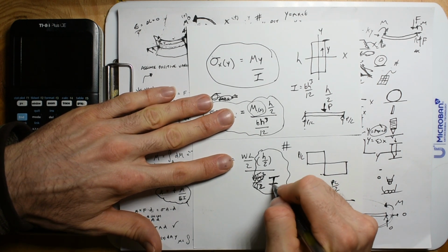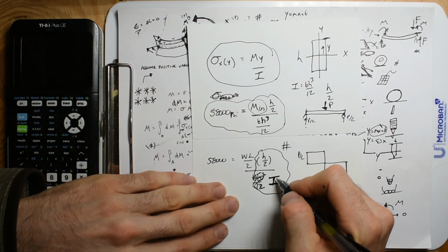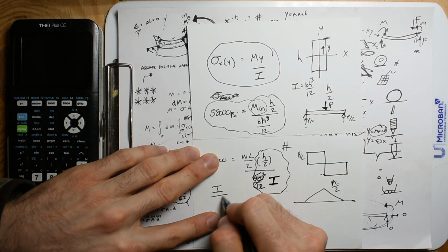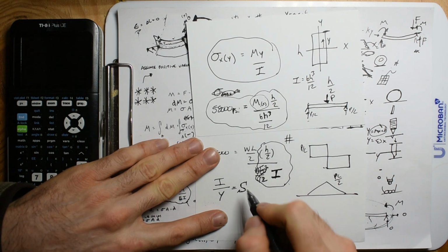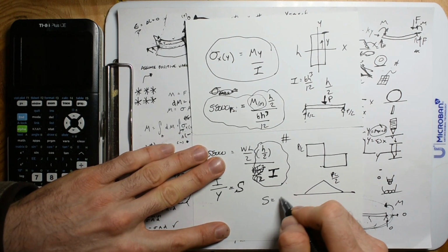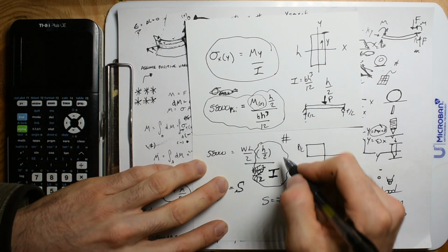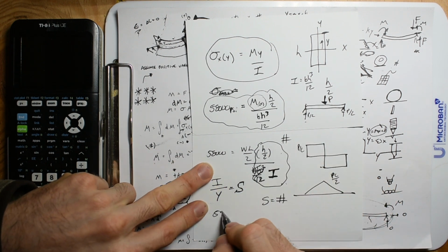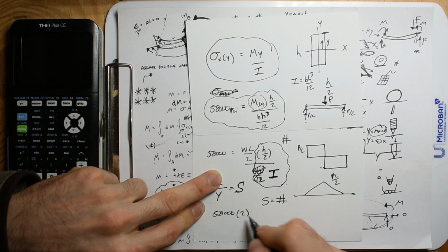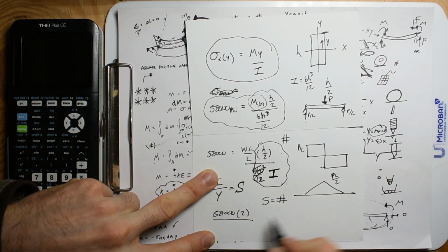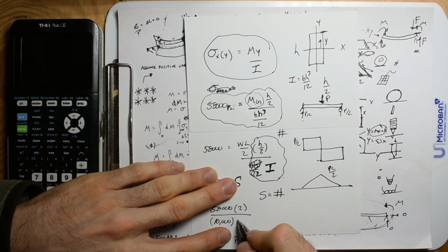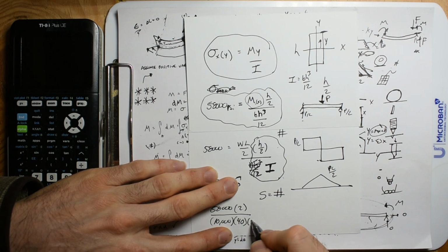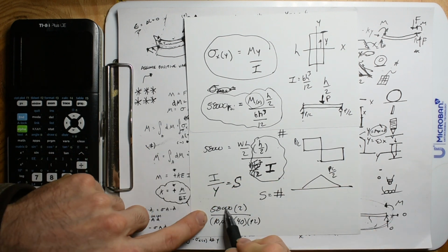We know the moment of inertia of a beam. And then this I divided by y, if you flip it, is actually S. Even though you don't need it, if you go to I-beam charts, this is just a number. So right here, I would just rearrange this equation. I would take 58,000 times 2 divided by the weight that I want the bridge. Let's say it'd be sweet to have a 10,000 pound bridge just to say I had it. And then the length is going to be 40 feet, or 40 times 12, because we need to work in PSI, inches.